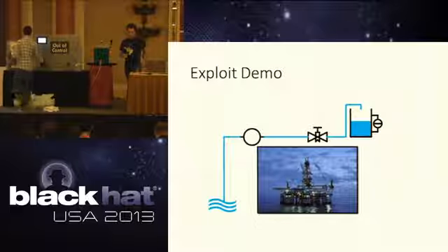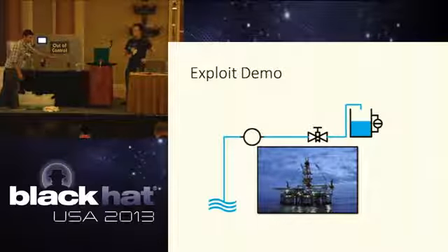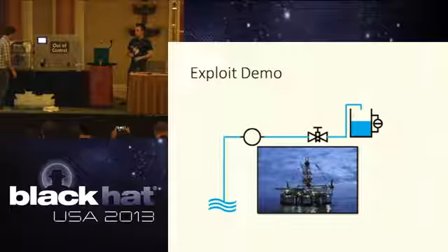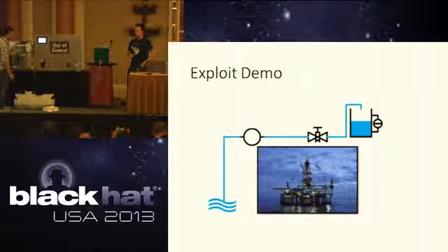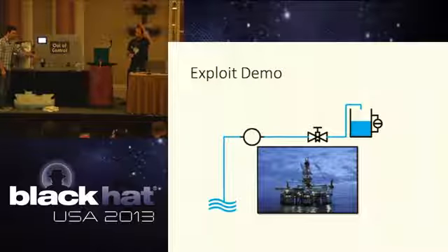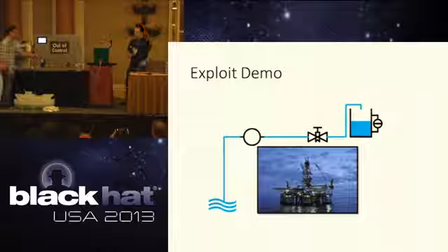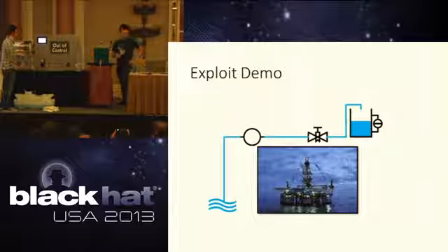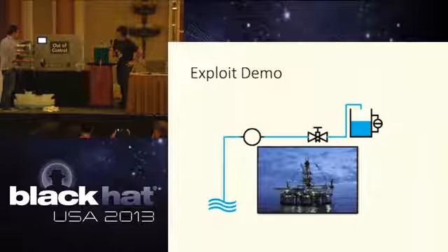And this is just a little 24-volt pump. This is just a tiny little 24-volt solenoid valve. But it doesn't matter, right? Because this PLC right here sends signals out to the field, and this could be a 24-volt pump or a 10,000 horsepower motor. It doesn't matter. It's just a signal. It just matters what we could actually fit in our car and drive here with.